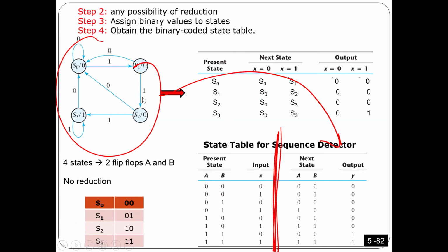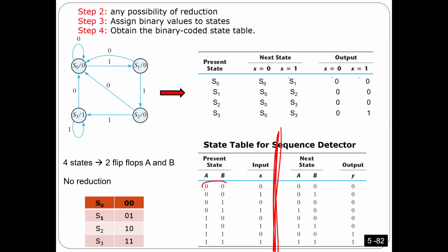So here you have to get this one from the figure. Let's see how we can make it. Again, it's similar to what I explained last time. If you see here, the state is 0, which is state 0 here, and the input was 0. Based on your design, what should happen when the state is 0 and input is 0? Number one, I have to stay in state 0, that you see here, and the output has to be 0. Make sense?